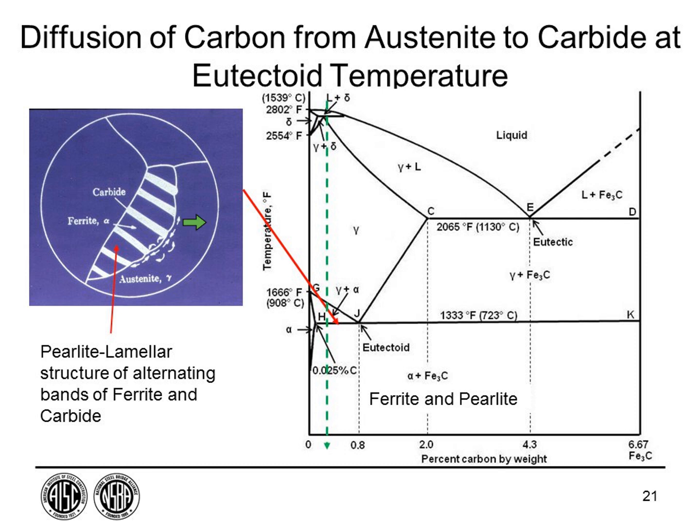And we get a lamellar structure, this layered structure of ferrite and carbide, and it's that structure that we call pearlite. So pearlite is a microstructure, not a phase, but it's very important. And a metallurgist would call our steels ferrite pearlite steels. And that would be the way they would describe them.